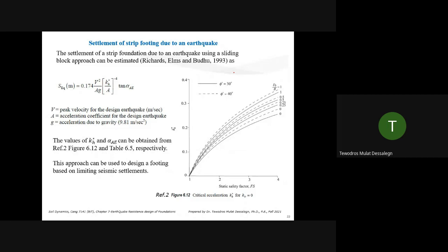They understood the seismic behavior of soil is different during an earthquake than in the static condition, and they started developing these tools. They didn't have full finite element simulations in those days. So this is what they have been using. Nowadays, you may not have to use this. Just model it in the software and run it, and provide correct seismic soil strain compatible properties, or constitutive models.